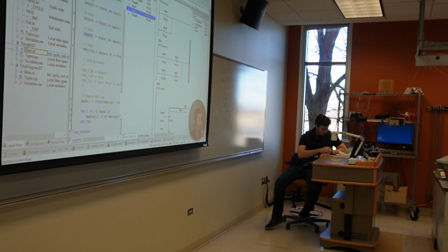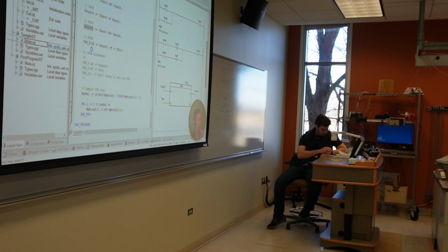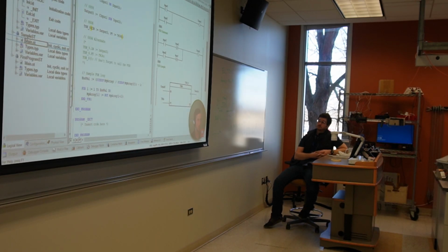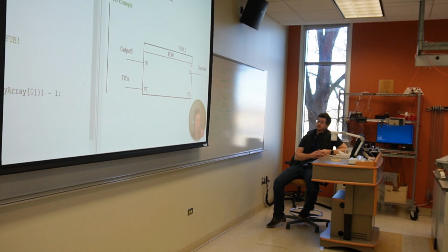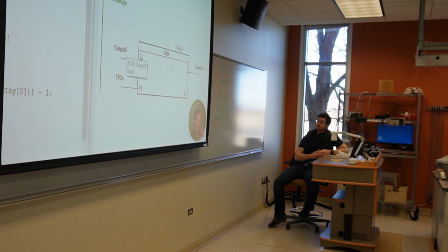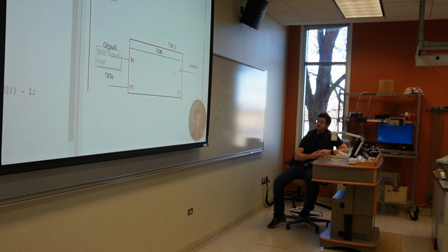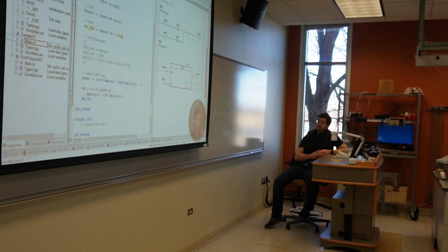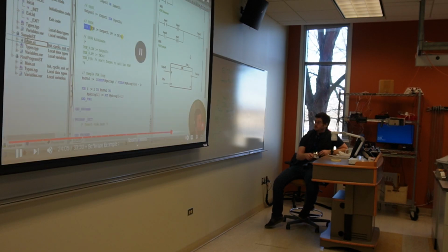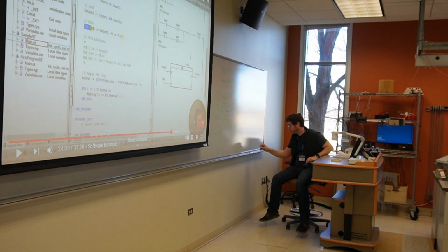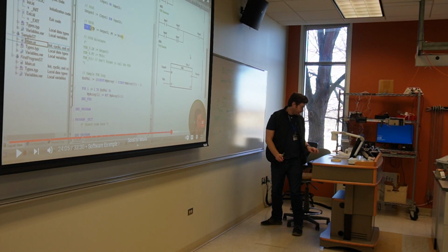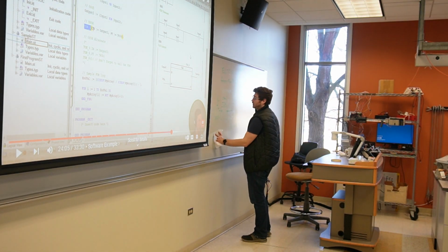Okay, so moving on, let's look at function block call. So we'll look at the two different ways here. As a reminder, this is what it looks like inside of ladder. You've just got a graphical representation of your function block, and then you're tying the inputs and outputs to it directly. Here we've got the inline function block call. Okay, so ton_0 is the name of the function block.